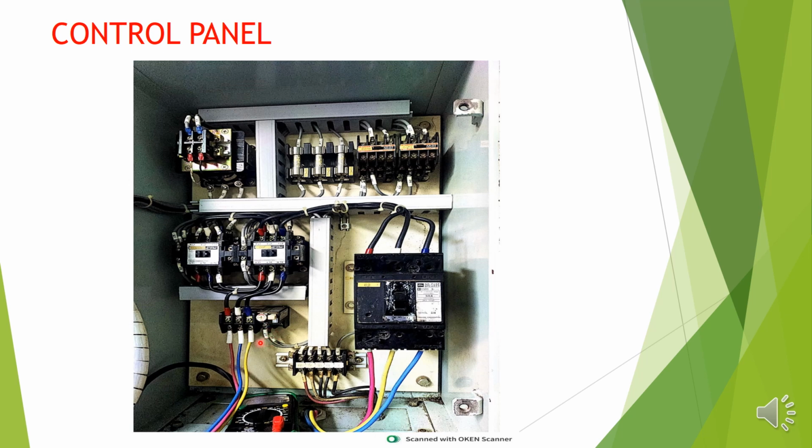After that 95 96, you have to check the push buttons, that is the stop push button and emergency stop push button, that is already inside the panel, in front of the panel, that everybody knows, the stop push button and start push button. Okay, that you have to check by using the multimeter by continuity.